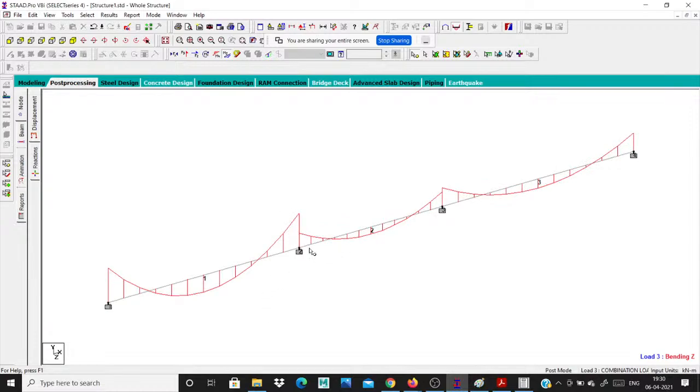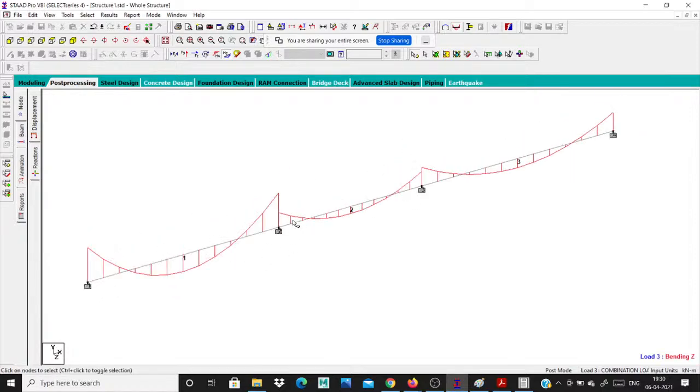There is some difference. What is the difference between different types of bending moment in this fixed condition, right? These are different types of beams supported for fixed conditions. This is a moment. The simply supported is different. The fixed condition moments are really different, right? Okay. This is our moment. The simply supported means only a tension zone, right? Only a tension zone for moment. Fixed and continuous means the moments will come from the compression zone also, on two sides, right? See this difference. This moment diagram and this diagram.